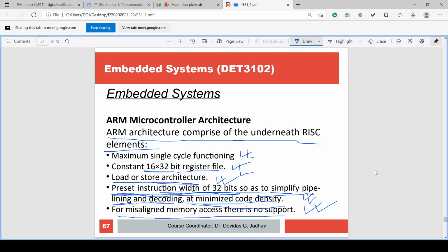Now, if there is no problem with execution of serial instructions, then it can be very fast execution. But if there is a jump, then we have to erase or flush all the 4, 5, 6 instructions fetched, and fetch new instructions according to the jump decision. So this is how the pipeline works.